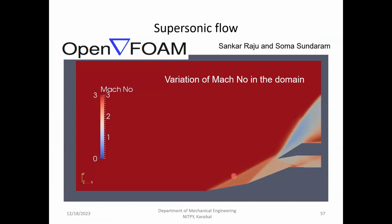You must get the dimensions and then specify. In Fluent, if you want to give a mass flow inlet, you can go to that boundary, change it into mass flow inlet, and then give the velocity, temperature, and pressure values.